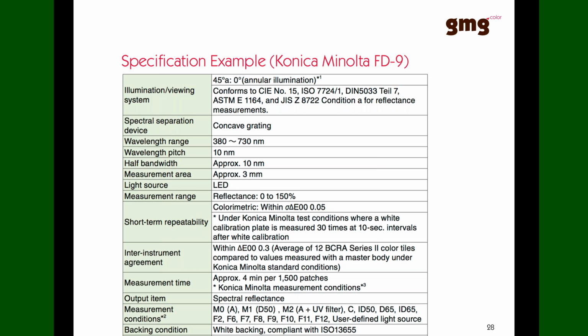And then here's also some information about the inter-instrument agreement. So Konica Minolta measured the BCRA tiles, the ceramic tiles, and compared those measurements to their master body, and they reached the value of delta E 2000 within 0.3 delta E.